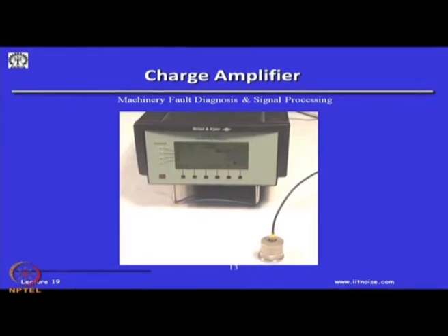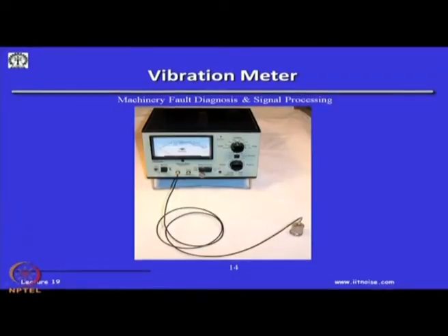When you are talking about underwater accelerometers or hydrophones, we have underwater accelerometers wherein you can measure the vibration of underwater structures, but the cables there are very costly. They will not allow water to seep into the conductor and contaminate the readings, etc. Okay. And this is a uniaxial accelerometer with a top connector, and this is a gold plated connector to make sure that there is no corrosion, etc. And this is that cable here, which goes to a vibration meter, wherein you can select the knob to see the readings of either acceleration, velocity, or displacement. Okay.